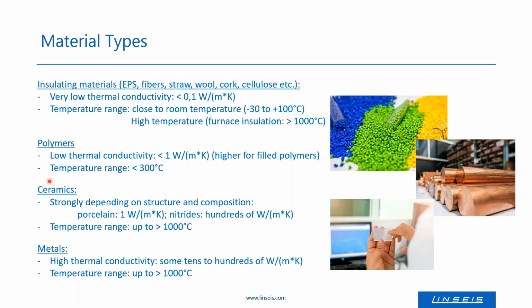Ceramics may be used at low temperature, but also at high temperatures higher than 1000 degrees centigrade. Metals have high thermal conductivities, usually in the range of tens to hundreds of watts per meter Kelvin, and the application temperature may exceed 1000 degrees centigrade as well.